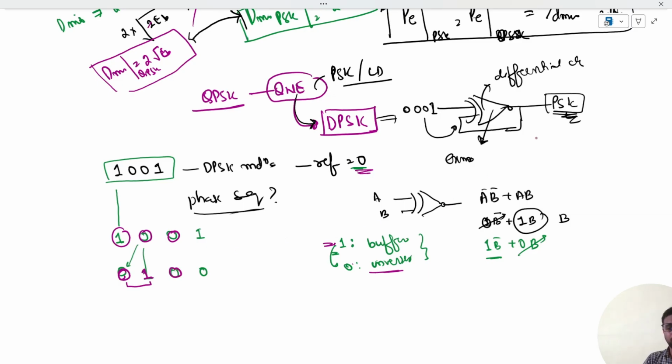Why? Because here in the circuit, we see the output is already given as one of the inputs, and this is the control input. Depending upon this being 1 or 0, the output will change. So the output is 1, it becomes 0. Now again, 1 is given over here, so whatever the input is over here, it will be the same at the output. The previous output is the input. Previously, what was it? It is 0 only, so next will also be 0.